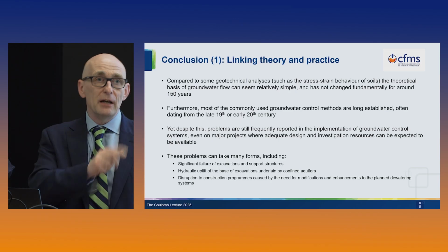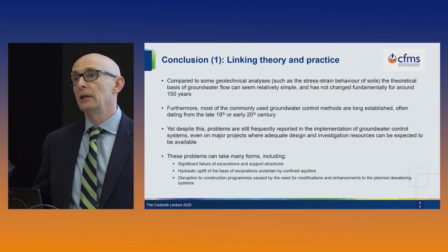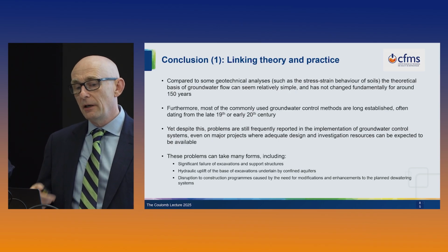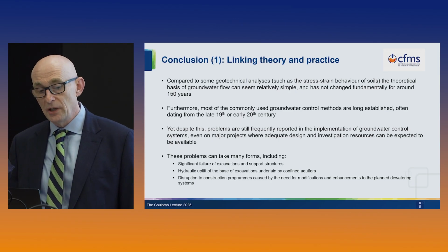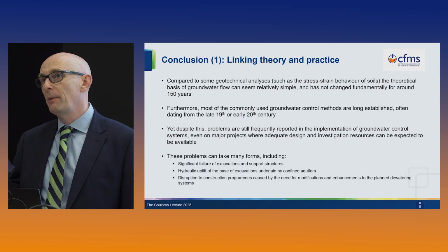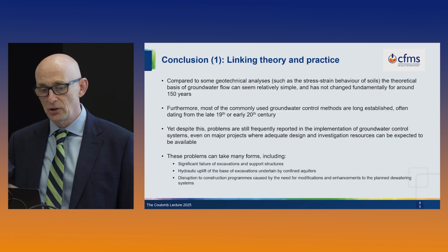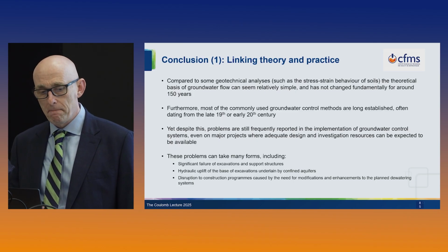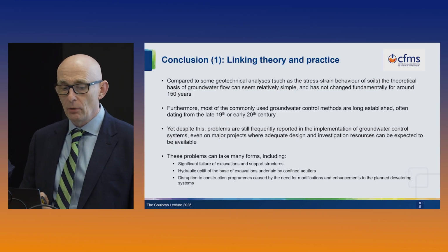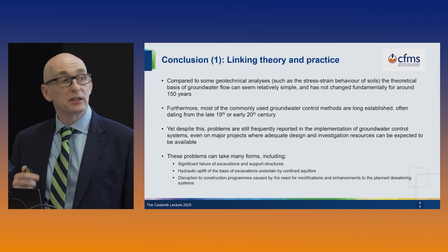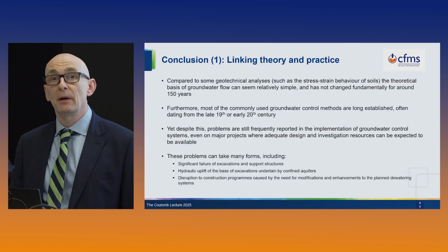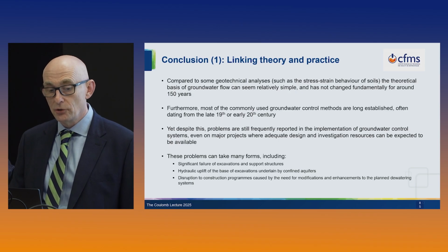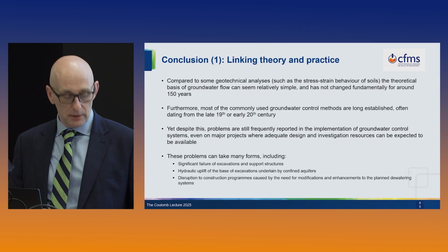But despite the fact the theory is long established, the principles and methods haven't changed, we still get, in my experience, frequent problems reported with the implementation of ground control systems, even on major projects where you would expect there to be adequate resources for investigation and for design. These problems can take many forms, including significant failure of excavation support structures, hydraulic uplift of the base of excavations underlain by confined aquifers, and disruption to construction programmes caused by the need for modifications and enhancements to the planned dewatering systems.